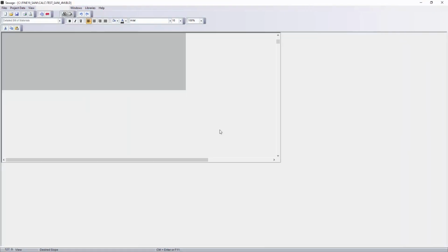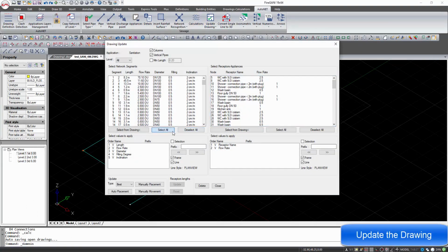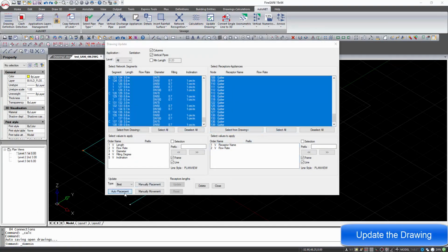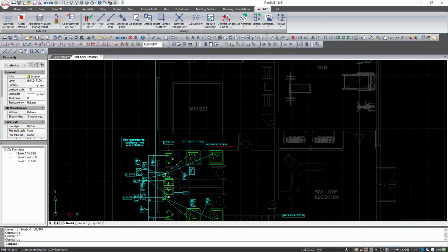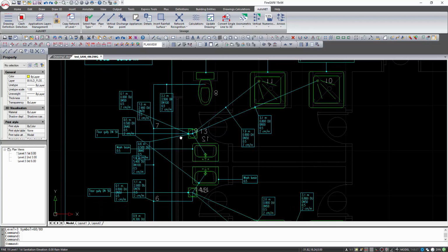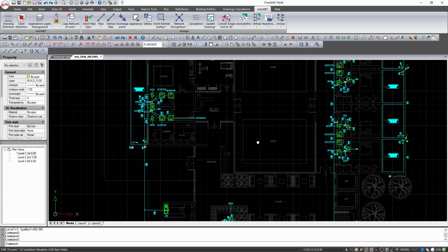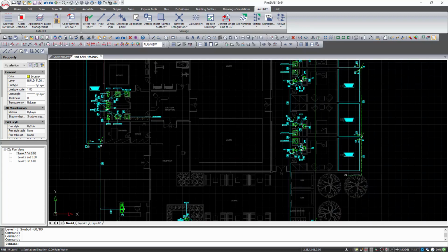When the calculations in the program Adapt are completed, you can store the project. You can refer to the drawing program Fine and select Update Plan Views. With this option, the calculations regarding the piping are transferred to the plan view. If this action was already carried out earlier, the program will ask if the user wants to delete the previous update and replace it with the new one.